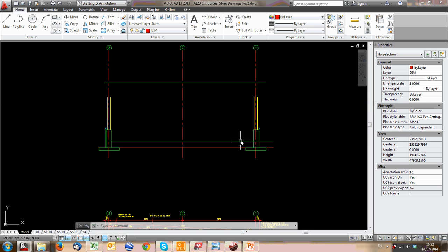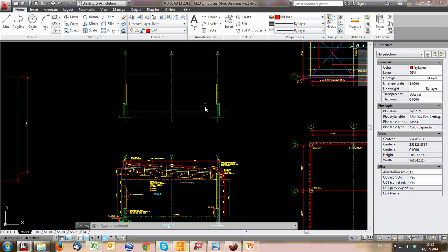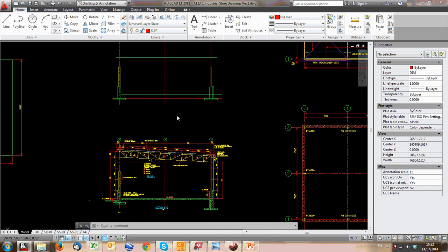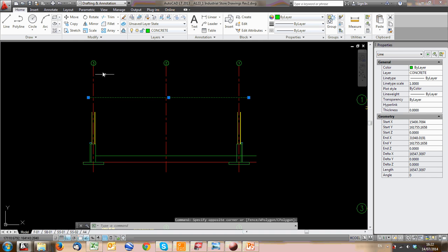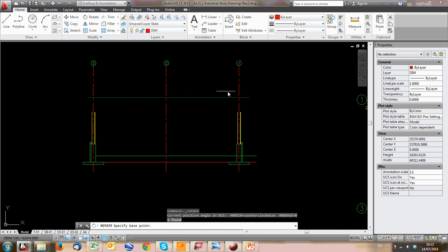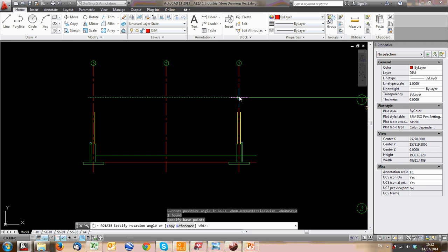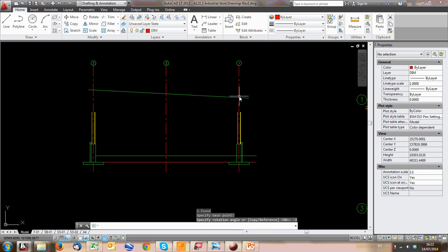So I've got 6 meters up, a line going at 3 degrees off. So let's start creating that. And then I'm going to have a 1 meter deep truss on top. So what I can do is select this line and rotate it. Click on rotate. Point there. And I'm going to select -3 because the direction has to go -3. Alright, that is now at 3 degrees.